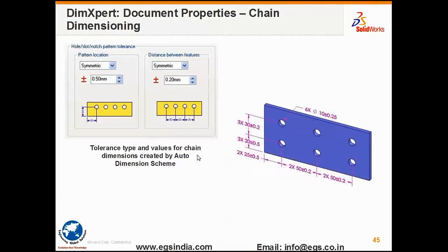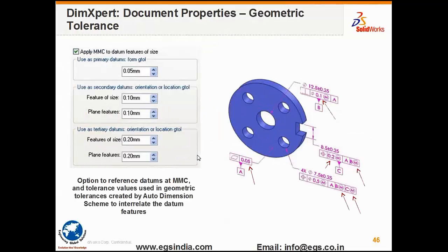The classic advantage of DimXpert is not only building in the knowledge base that is required for correct and complete specification of the tolerances, but also to ensure that user upon user produces it in the same standardized manner.